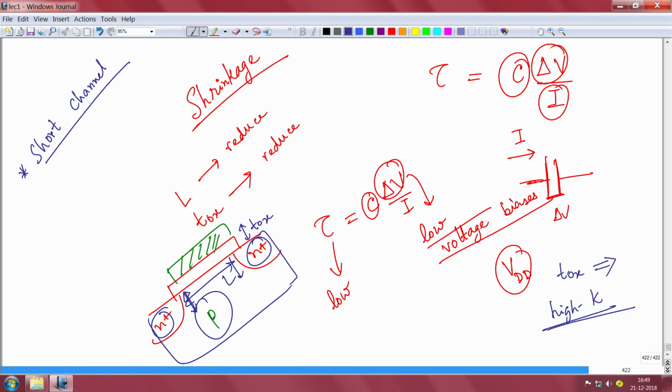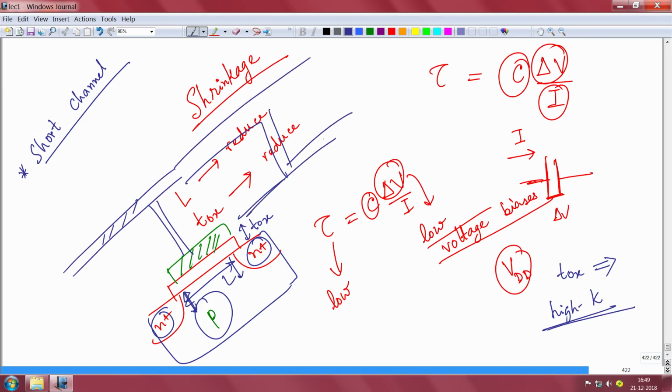There are things like strain channel, germanium silicon alloy strain channel, where you can enhance the mobility of holes, for example. You are talking about new types of metal contacts, polysilicon contacts, and interconnect delays have to be reduced, because there will be multiple layers of these transistors that you have to connect from many lines. These are called interconnect lines. You know, from one transistor to another transistor you will have lines. These interconnect lines also will lead to parasitic resistances and capacitances. You have to reduce the interconnect delays.